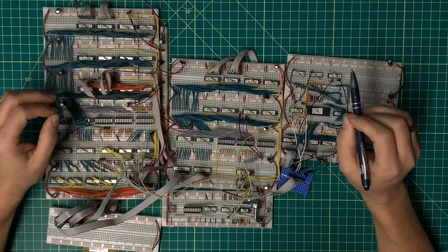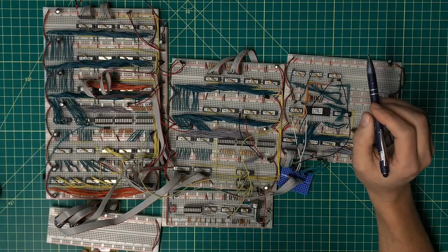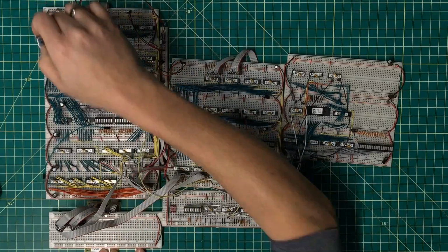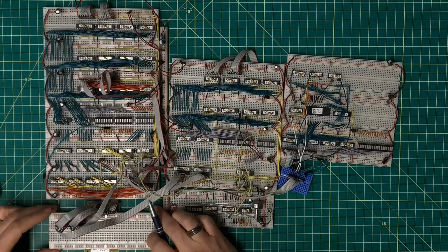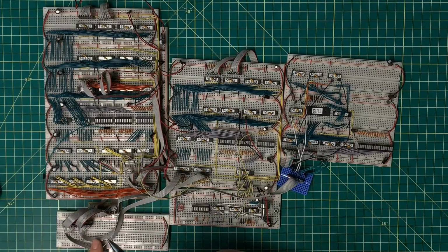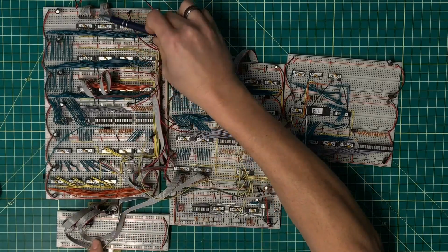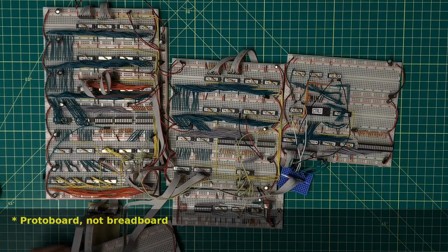All right, before I go and plug this in, let's take a moment to reorient ourselves as to what we're looking at here. This is my prototype register, and I'm going to use this as the program counter for now. This is my stand-in for memory. I joke that this is carefully architected such that every single memory address contains its own address as its contents. The reality is I've just got the address bus 1 assert lines looped all the way down here, coming onto this breadboard here, which is my address bus 1.